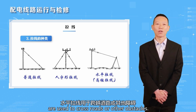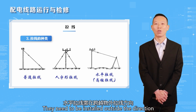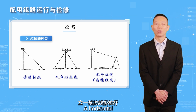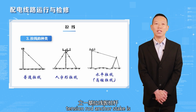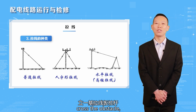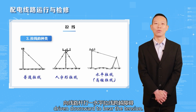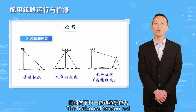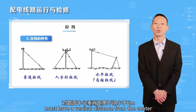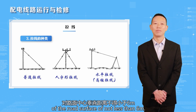Horizontal tension rods are used to cross roads or other obstacles. They need to be installed outside the direction of the obstacle to pull the line. A horizontal tension rod anchored stake is set upright at the base of the line to cross the obstacle, while another tension rod is driven downward to bear the tension. The horizontal tension rod crossing the road must have a vertical distance from the center of the road surface of not less than 6 meters.